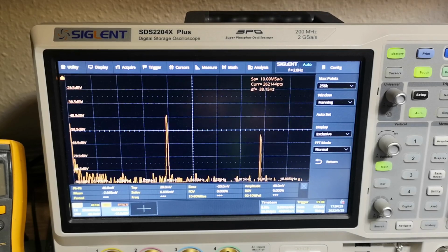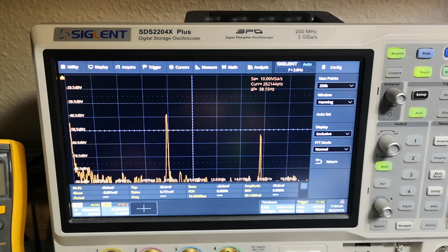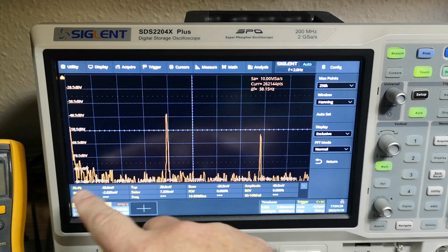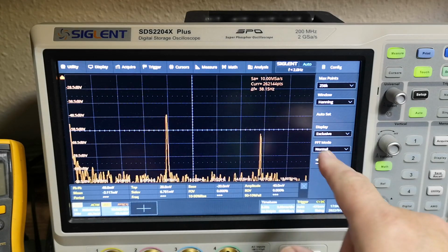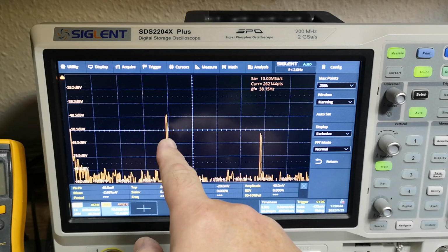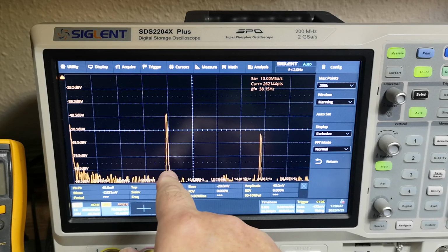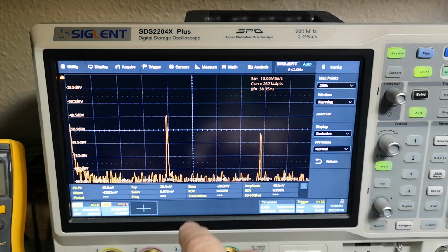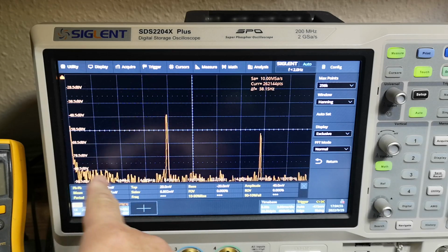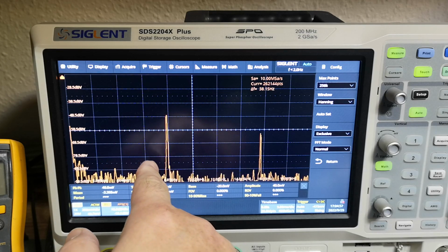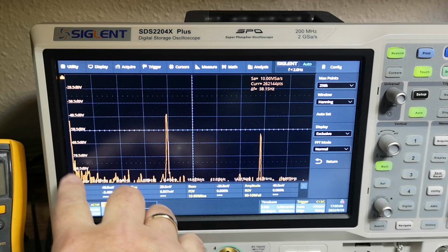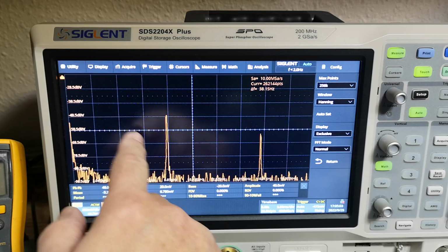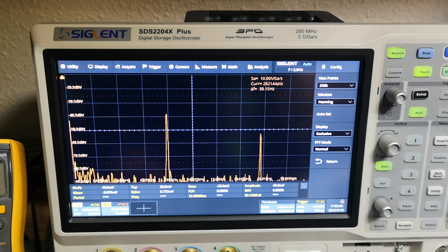I think it is a little bit easier to show you guys the output from the modulator in spectrum analyzer mode. So now I'm in audio range from 50 Hertz to 20 kilohertz. This is the 8 kilohertz modulation oscillator input, and this is 16 kilohertz, the harmonic of the input oscillator. And obviously all this area down here, this is the output range after all the filters and stuff. So this is where the audio will be, right?